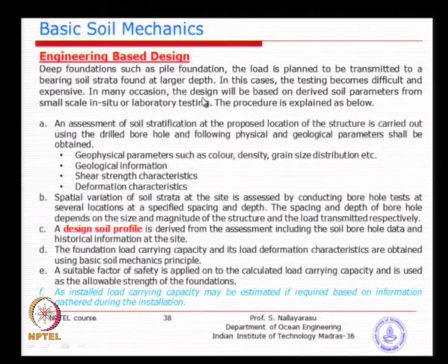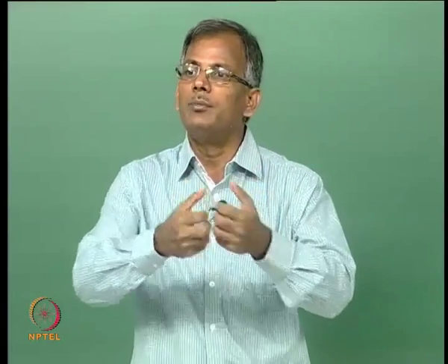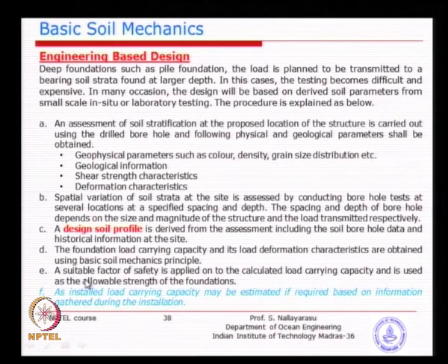So, the engineering based design has several uncertainties, I would say. Now, you can see the difference. If it is testing based, the uncertainties have been removed by doing the testing, whereas if you do not have testing, there is going to be a large variation in soil characteristics if it is a larger structure, and because of that we need to apply a margin of safety. When we discussed structural design, even though steel is a well known material, we still applied a margin of safety, where we divide the yield strength by 2 or multiply by 0.66 depending on the nature of loading.